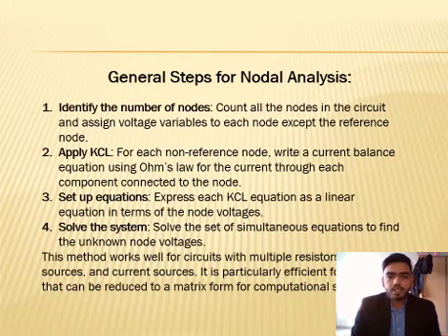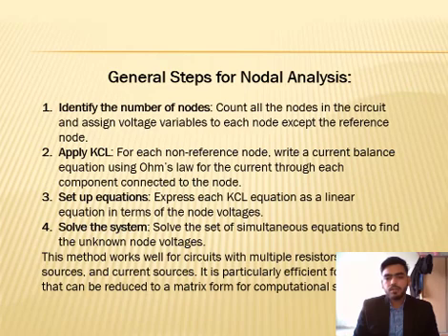General steps for node analysis: identify the number of nodes, count all the nodes in the circuit, and assign a voltage variable to each node except the reference node.